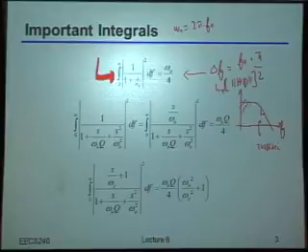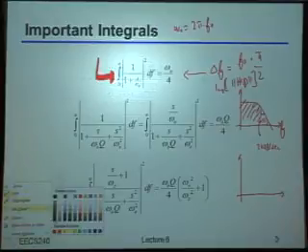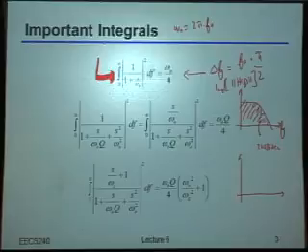Yeah, I'm taking the whole area under the curve. Okay? So what would this curve have to look like? And let's draw it again over here, maybe even in a different color. What would the shape of that filter need to look like in order for you to get exactly the cutoff frequency as your effective bandwidth?